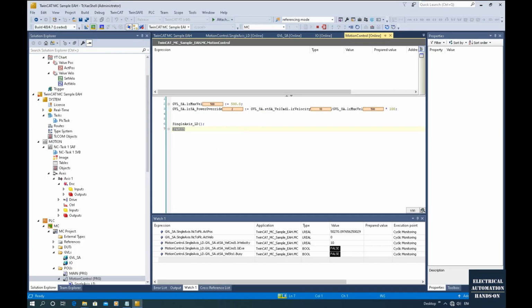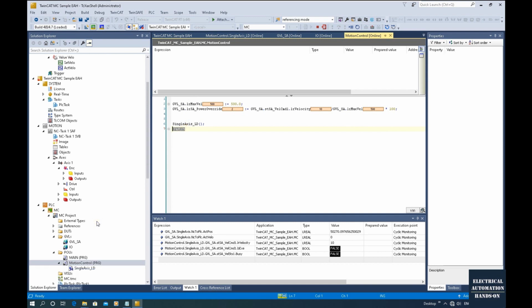This is my actual target: I sent 10 millimeter per second, and this value will be under this maximum velocity. We arbitrarily set 500. This 500 is an arbitrary value. In an actual case, you need to set the maximum value higher than any command you need to send to the velocity. And then this maximum value needs to be set to the MC velocity.